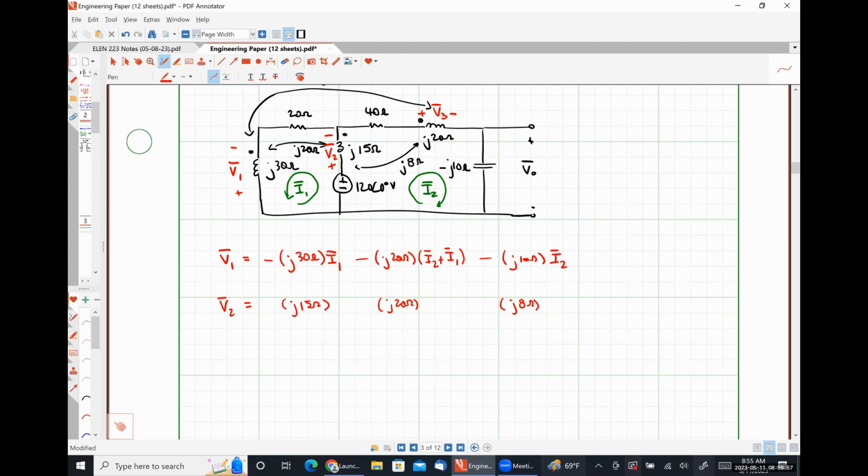All right, so I2 plus I1 is flowing into the undotted terminal. So I1 plus I2 here will give me a plus sign out here. Then I have my coupling with coil 1. So because the positive polarity terminal of V2 is associated with the undotted terminal,